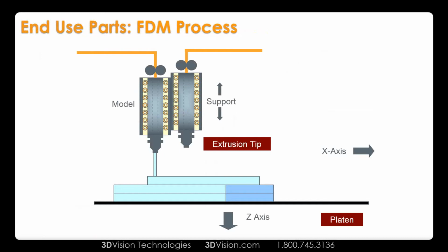Now, doing it layer by layer, basically from the bottom up, or inside out, I like to say as well, is we don't have to build it solid. Right? We can do a sparse fill where we just have a very little amount of material in the middle just to hold it, to help it keep its shape. So if you just need a product mock-up, maybe on that first stage of production, where you're trying to set the flow through the shop, this is all you're going to need. You don't necessarily have to have it solid. Right?